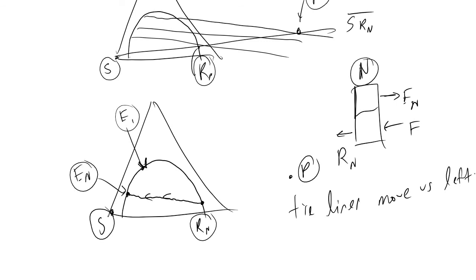And we now use our pivot point to tell us the relationship between E_n and the incoming R sub n minus 1 on the opposite side of our two-phase region in our plot. To do that, we draw a fictitious line between E sub n and point P, and we see where this intersects our two-phase region in our ternary plot.